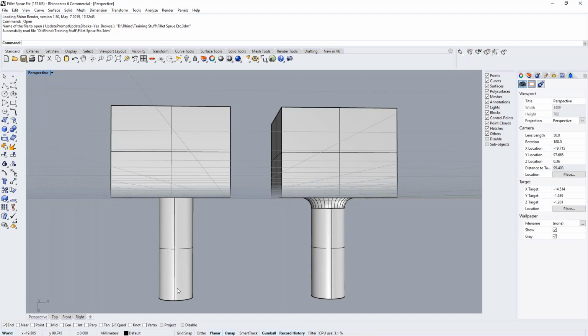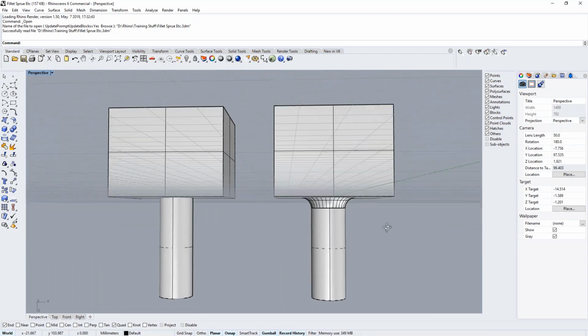So imagine the casting process. We have high density metal, high density fluid coming up here at very high velocity. This little sharp edge of investment often has a tendency to break off and get lodged somewhere in your object. If it's lodged in the middle of a solid piece of gold, silver or platinum, you may never know it's there, and it might not create a problem. But a lot of times these things get lodged on or near the surface, and that's a big thing with pits and porosity. On the right-hand side, you see the way to make that better.